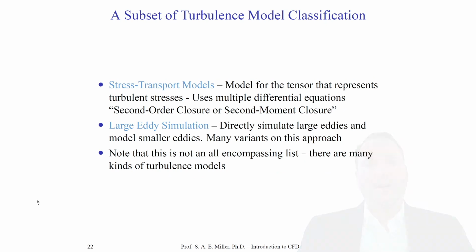There's also what we call stress transport models, and these might transport the stress tensor of the turbulence. And this uses multiple differential equations too. They might be called second order closures or second moment closures. We'll look at these in this class.